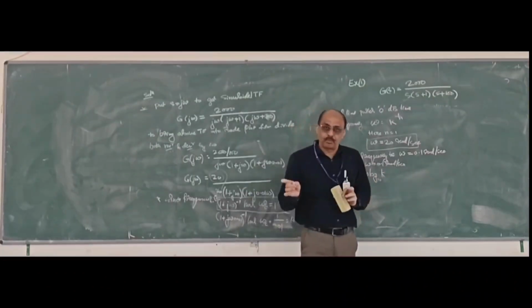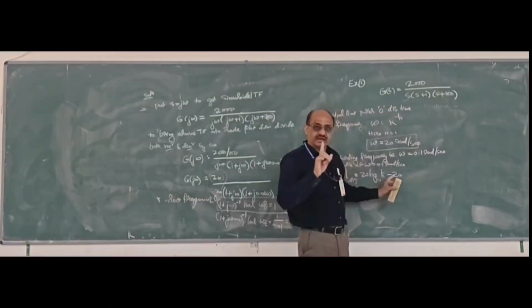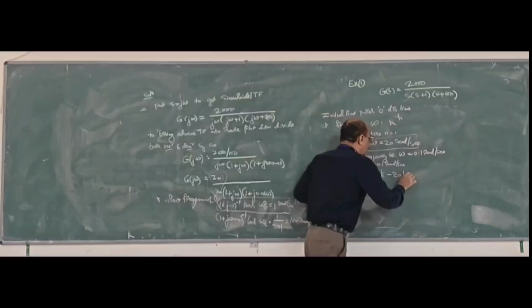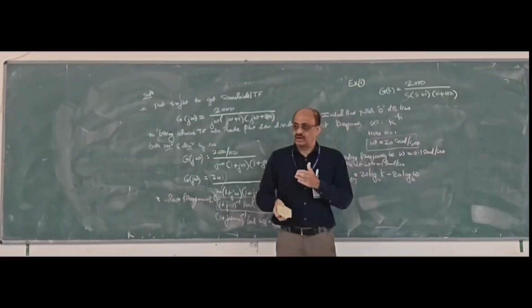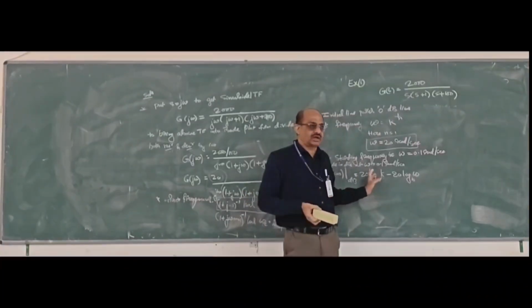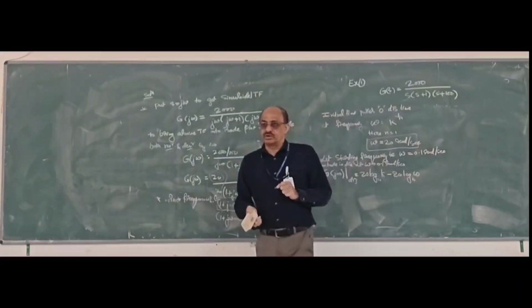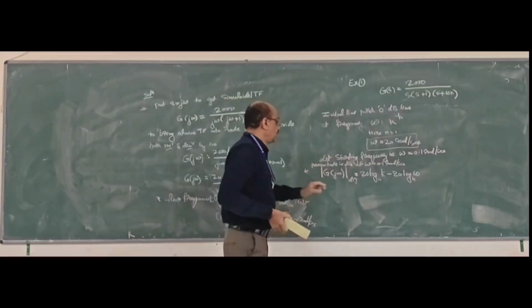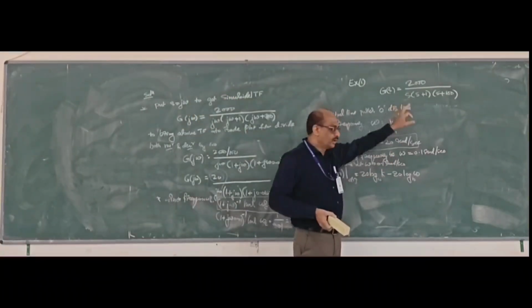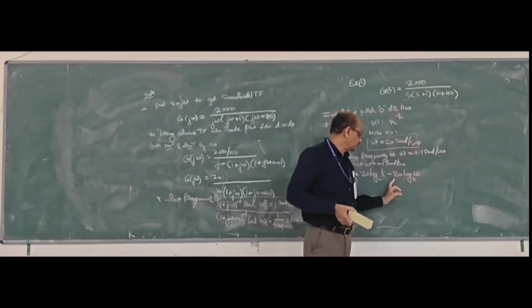Because it is a pole, it is minus 20 n log omega. Look at the equation given there: minus 20 log k plus or minus 20 n log omega. It is minus because one pole is there, n equal to 1, s to the power of 1.